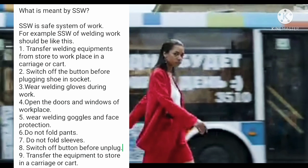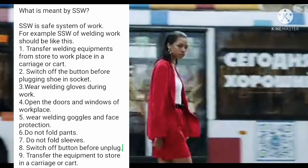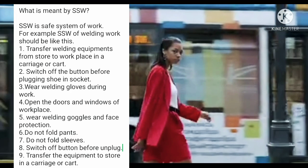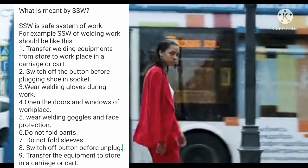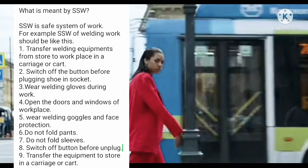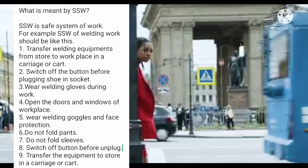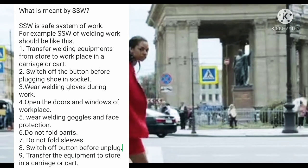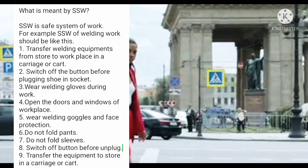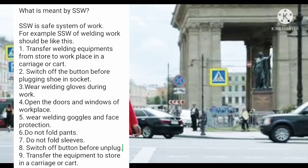What is meant by SSW? SSW is Safe System of Work. For example, the SSW of welding work should be like this. 1. Transfer welding equipment from store to workplace in a carriage or cart. 2. Switch off the button before plugging the shoe in the socket. 3. Wear welding gloves during work. 4. Open the doors and windows of the workplace.